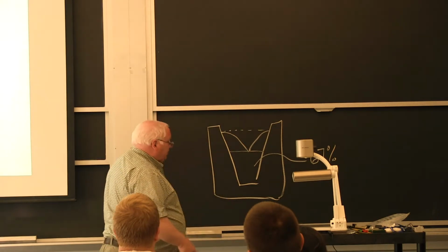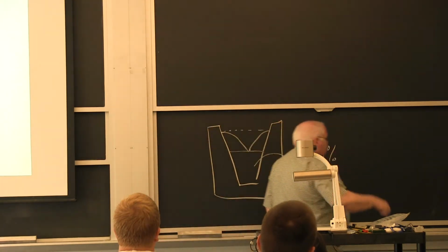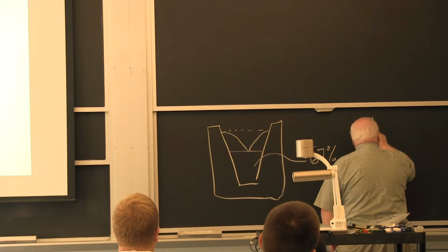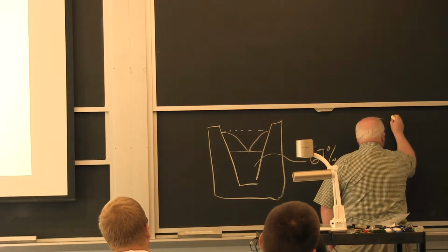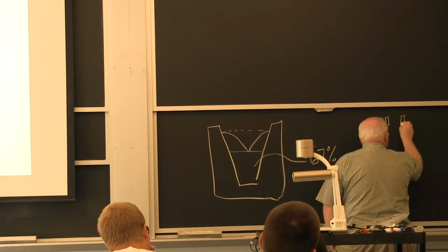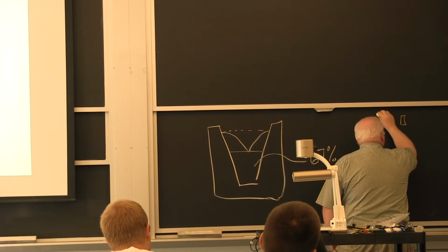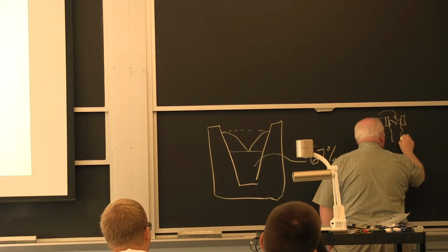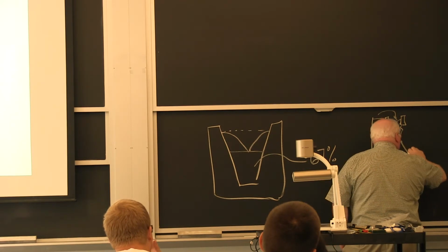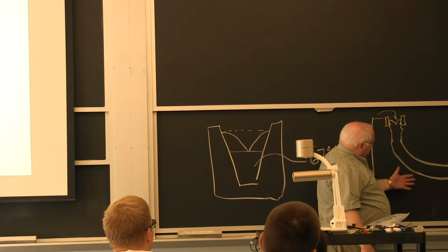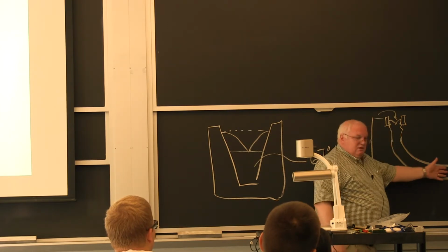If you do a continuous caster, which is a machine that's about 10 stories tall and cost $100 or $200 million back then, you basically would have a vibrating copper mold up here, water-cooled copper. You'd pour the steel in, and your shrinkage would be right here, but it would shrink down along the sides, and then you would bend the steel on the lower 8 stories, a hot beam of steel, and it comes out.